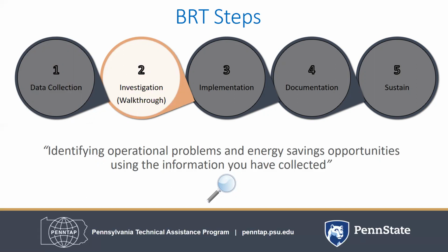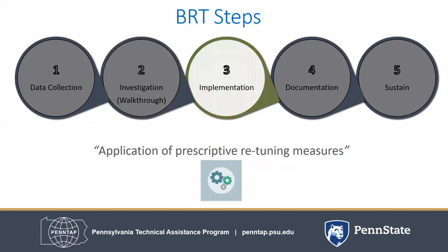There are many areas to investigate during a walkthrough, such as your lighting, your building envelope, all parts of an HVAC system, your hot water system, and your air distribution. Also, remember safety first. During your walkthrough, make sure to consider the nature of each system. High temperature equipment, electrical configurations. Make sure to wear the proper protection equipment. Consider ladder safety if you're going on a roof, and other safety precautions as they pertain to you.